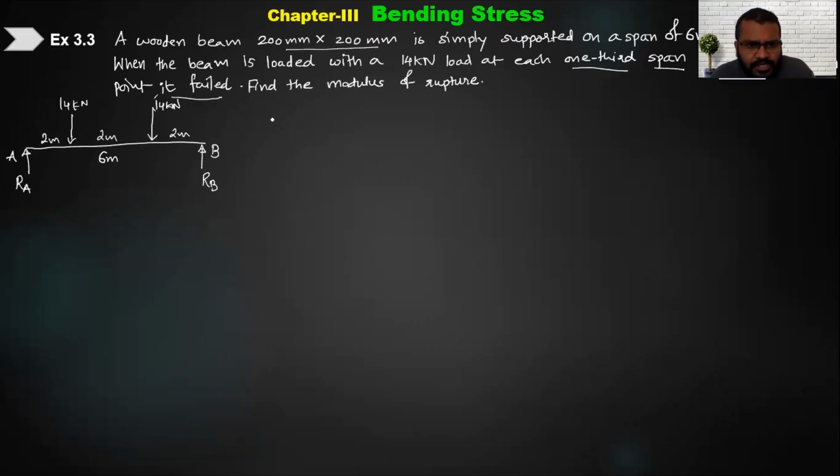That basically section modulus. तो या फिर modulus of rupture कैसे find करेंगे? अब इसके पहले इसका cross section क्या है पता है? तो cross section they have given. The wooden bar, अच्छा 200 cross 200 बोला है तो I'll have to draw the square. तो ये है मेरा cross section of the beam. ठीक है. उसका centroid कहाँ से जाएगा फिर? ऐसे. This is 200, so the y is 100.